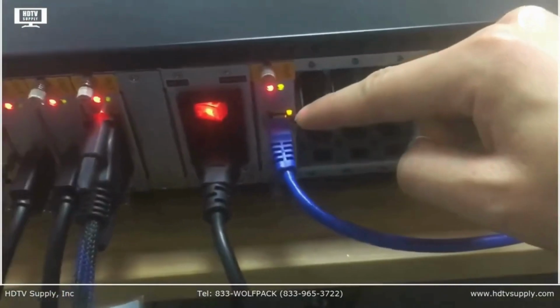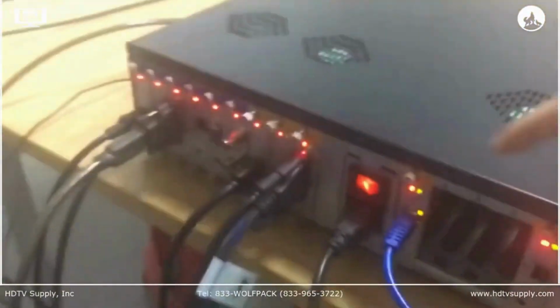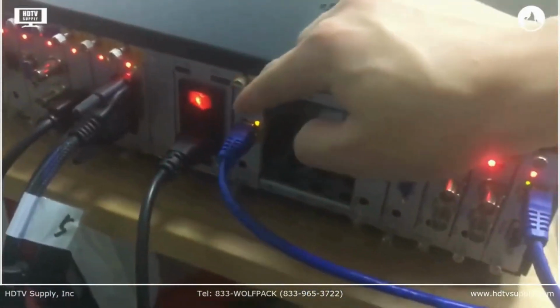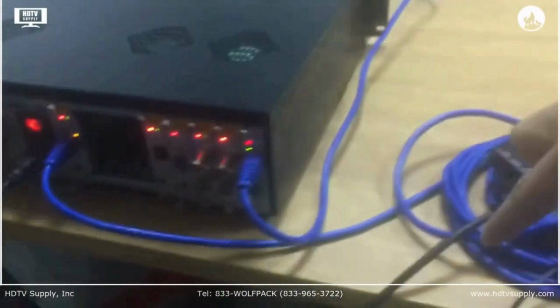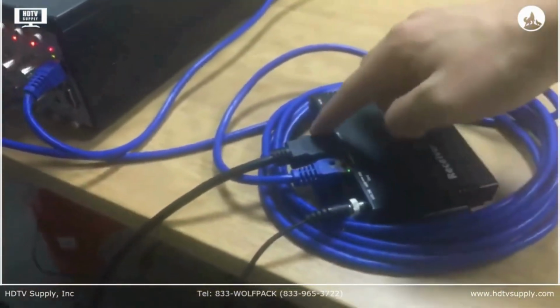For these 2 HDMI outputs, we'll just screw these 2 TVs on top. It's actually a 1x2 video wall. For the DVI, we go to TV 3 here. And for the HDBaseT, we have the Cat6 cable going to this receiver here. Then we get the HDMI output.